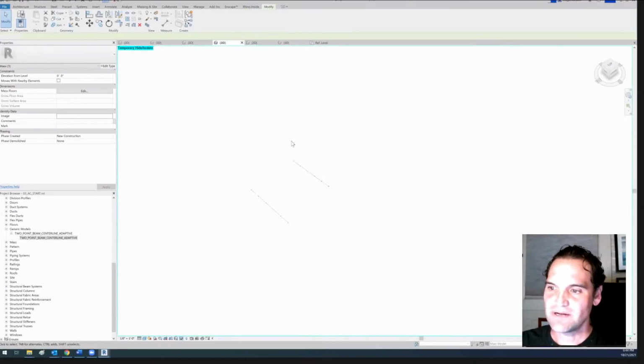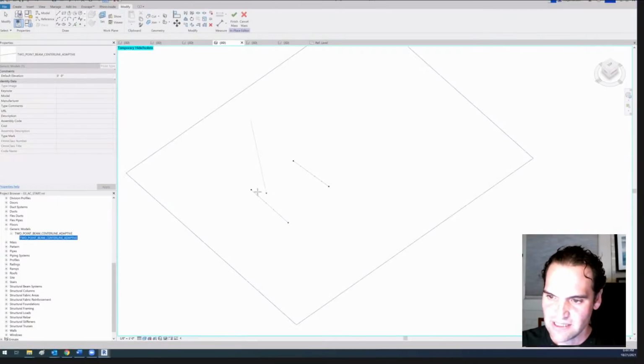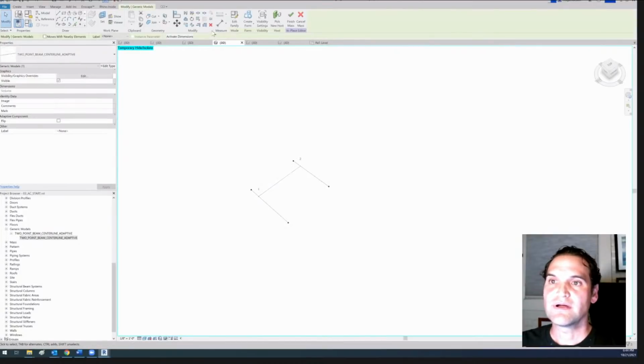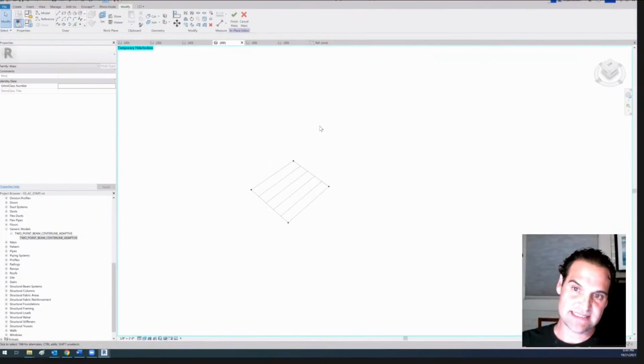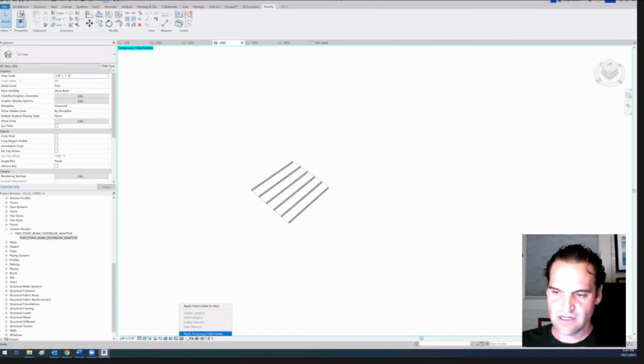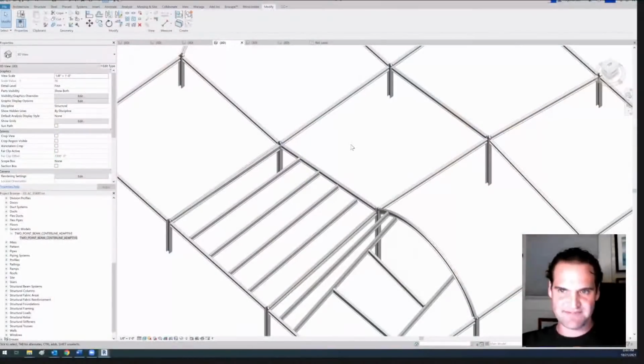So what I would do is I would take the adaptive component and I would actually place it on there. And then I would use a repeater under P, and then it'll actually place the adaptive components that way. And that's how I kind of mimic the BIM system. And then I can parameterize the divided path and so on. That's kind of the divided path method with a hybrid of Dynamo. Did you see how even if I put the divided path within the still family, it still grabs it? Dynamo, which is beautiful.